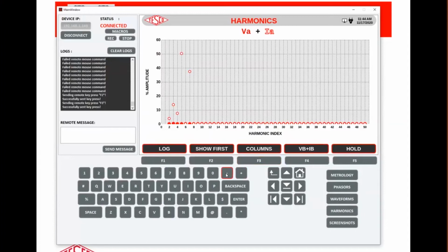So in a situation like this, we would have a case where the customer was generating harmonics that were causing us problems in our transformers and perhaps elsewhere. And we were having to oversize the transformers, yet unless he's billed on a power factor penalty or on VA, we won't get any compensation for that at all.